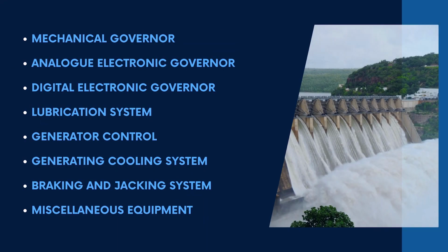Braking assists big machines to minimize bearing wear by restricting prolonged slow running before stopping. Impulse turbines have a separate reverse acting jet controlled by independent oil servo motors. When remotely controlled, these jets must be cut off when the machine has stopped to prevent counter rotation occurring. The heavier vertical machines require more powerful brakes in the form of oil jacks under the generator rotor, which press friction pads against a special rim, the pressure being applied through an air or oil reservoir.